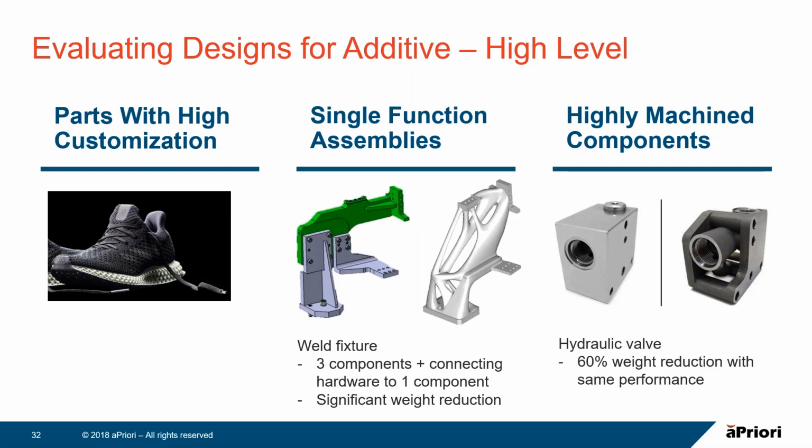Whereas for additive manufacturing, manufacturing that complex shape needed to connect those various mount points on this part is pretty simple, right? We've talked about how complexity within additive manufacturing is very, very achievable. So by changing their design to go to additive, this company not only reduced their part count significantly, going from 3 manufactured components to 1, they're also removing a lot of additional hardware. They're removing potential sourcing issues from having to source those 3 parts from potentially 3 different manufacturers, removing the assembly time. And they're also seeing significant weight reductions, right?